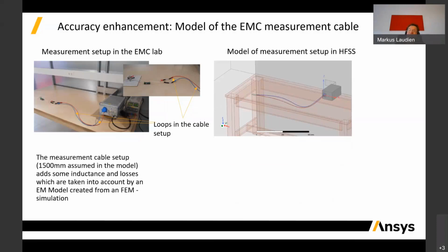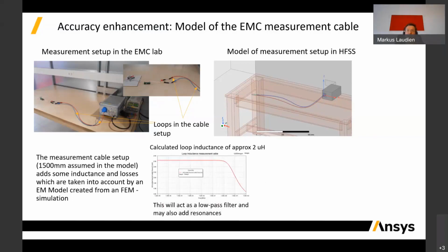And I've made a similar model. It's of course not the same; we could of course play around a little bit. I made some spacing in between the cable so that it looks somehow realistic, because we don't have the geometric information on how the cable was positioned. But it's about 1.5 meters in length. And in a first approach, I used a quasi-static simulation tool, which allows directly looking at the inductance.